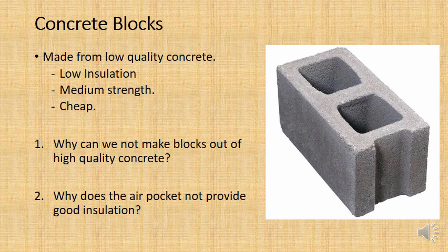That's what causes concrete blocks to be very poor insulators. If it was closed cell and the air were just bubbles inside the concrete, that would actually contribute to the insulation, but instead they're channels that run through the concrete, similar to Swiss cheese.